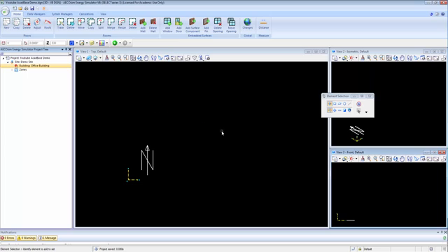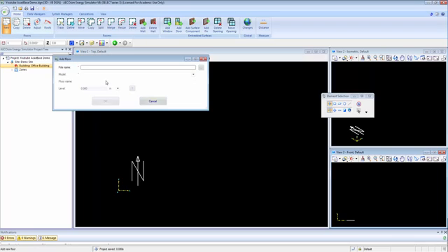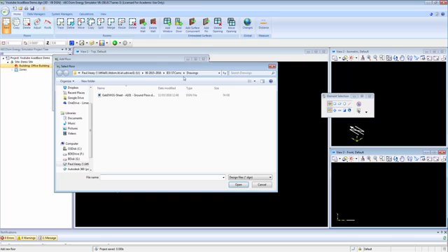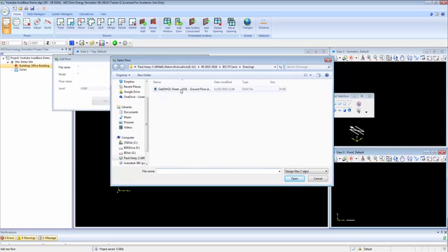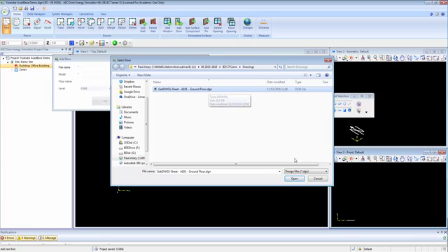And now we need to actually do something with the floors. So the way we do this is we work from left to right here. So we have floors, rooms, surfaces. So what I'm going to do is create a new floor. I'm going to call this, add floor, so that we need to get a file name first of all. So we go off and we find our sheet. So there's my ground floor plan, which is a DGN file. It'll work equally well with an AutoCAD file.